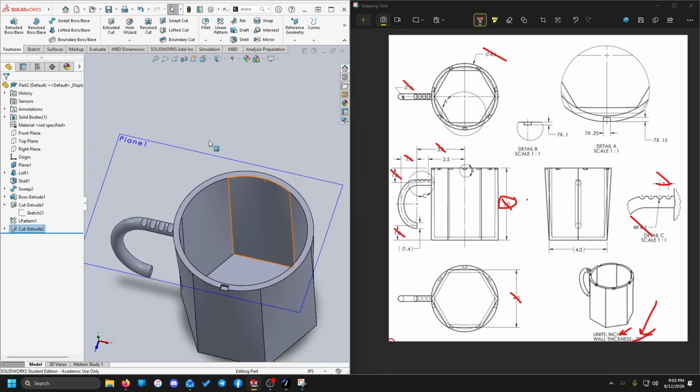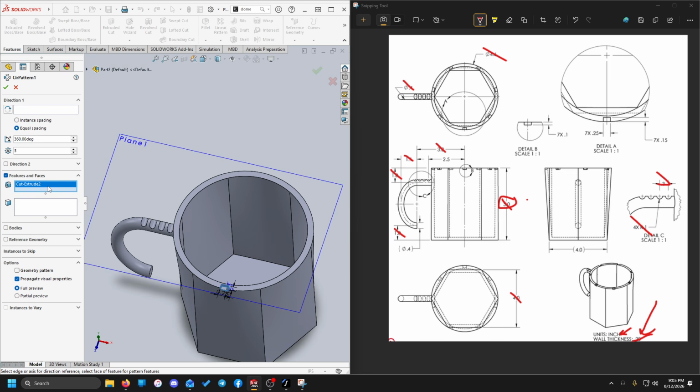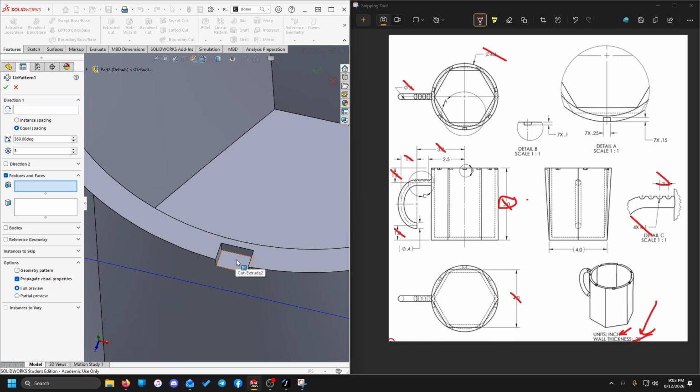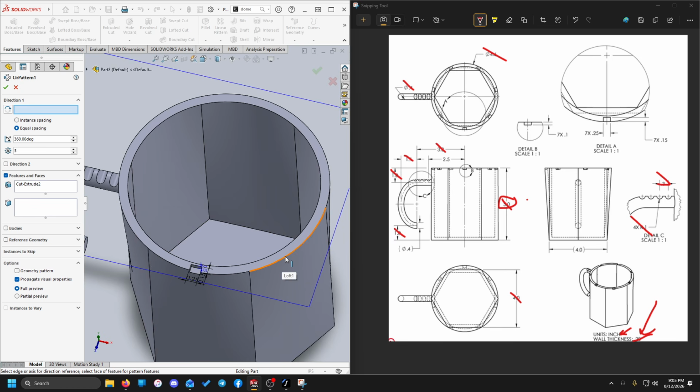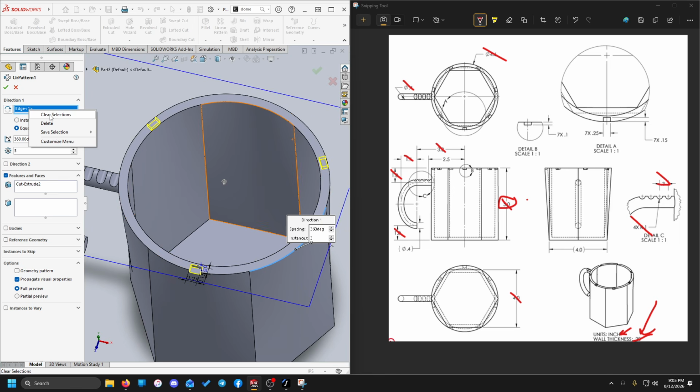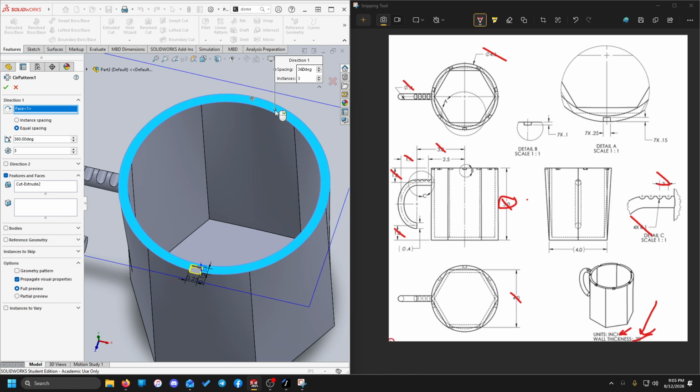Cool. So there's one. Then we need 6 more. So for that, we can use the circular pattern tool, where we want to circular pattern this feature. So we'll select that with our features and faces. And then for direction 1, we can use any circular edge. So I'll pick this in here. Oops. We don't really want to use the face because that can offset things a little bit depending on how SOLIDWORKS calculates it. I think actually if I select the face, is it going to throw...